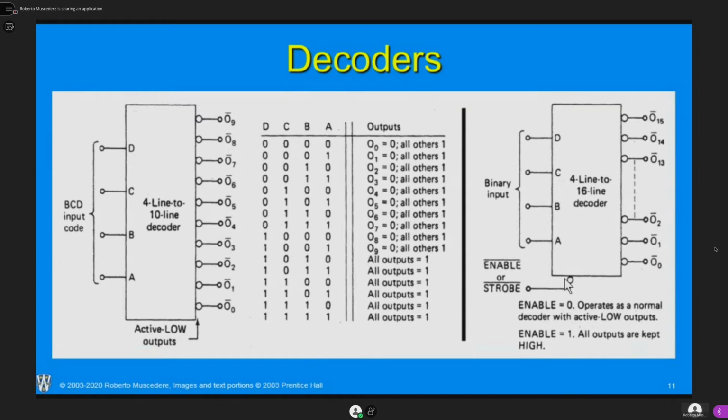Again, here they put a bubble to say that it's an active low enable, but some people might get confused by this having a line on top and this being a bubble. So which one is it, right? You just have to be quite clear and know. Again, I'm as clear as I can possibly be in the assignments. I'll state that it's active high input or active low output or something like that, but not every book or picture is that clear.